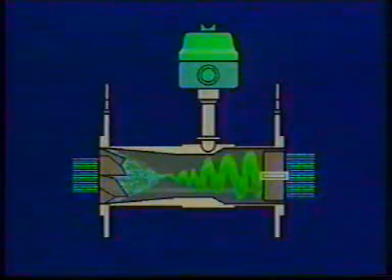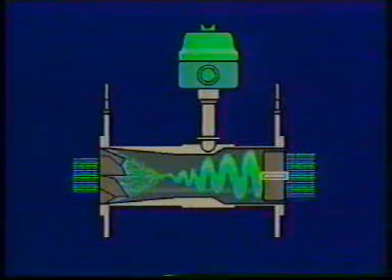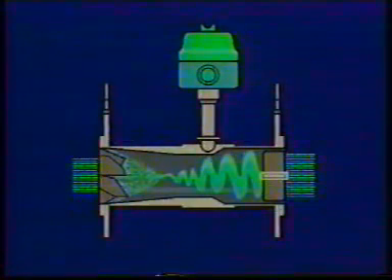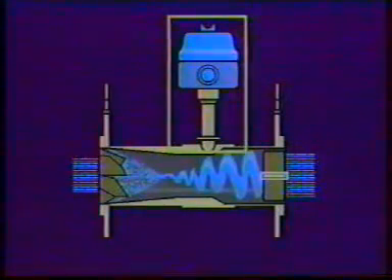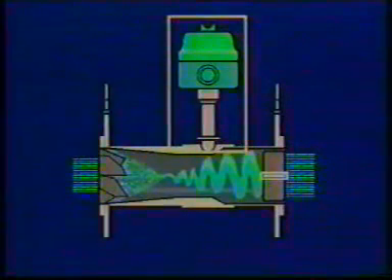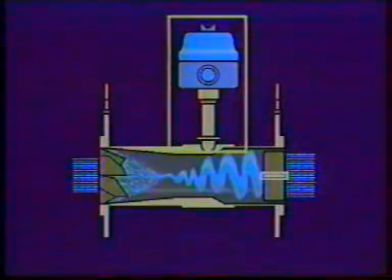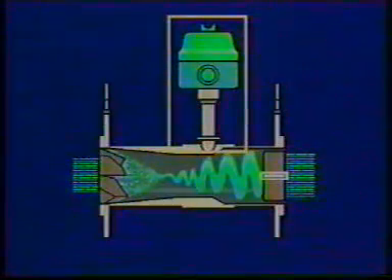The center of the swirl follows a helical path as it proceeds downstream through the enlargement. This helical path causes fluctuations in the pressure and velocity of the fluid. A sensor can be placed downstream of the guide vanes to detect and measure the frequency of the swirling precessions. This frequency is linearly proportional to flow rate.